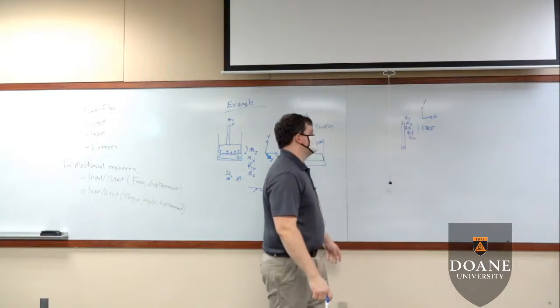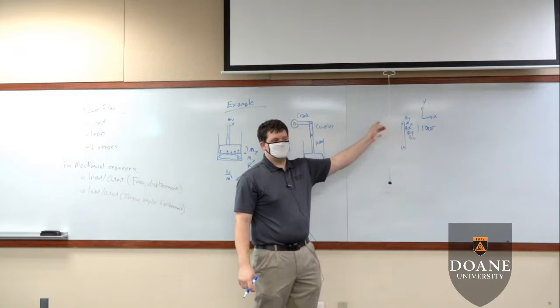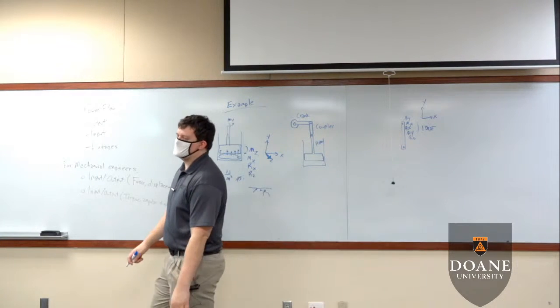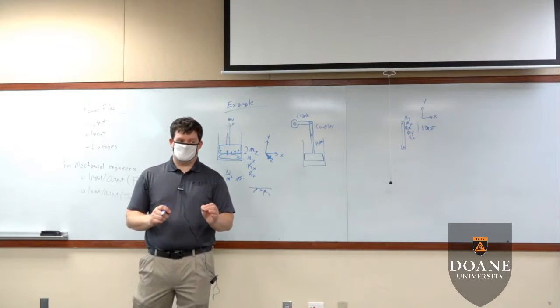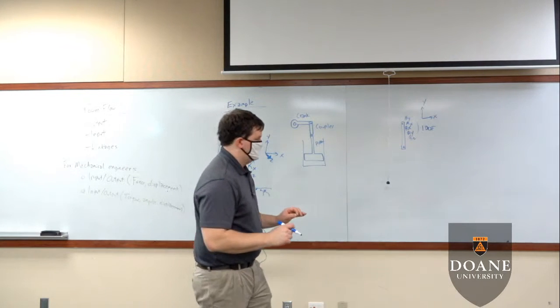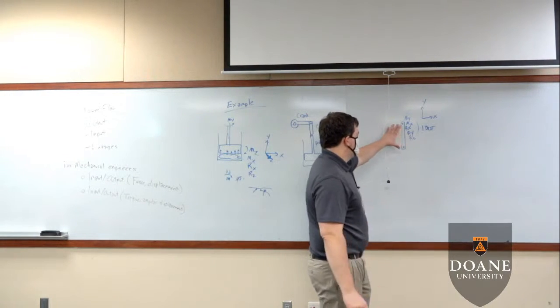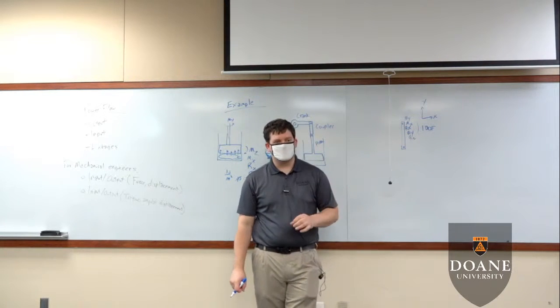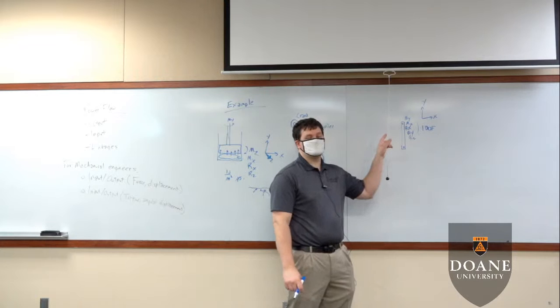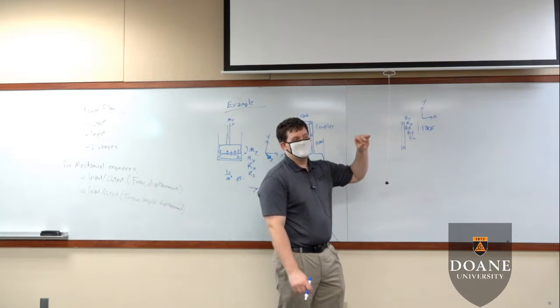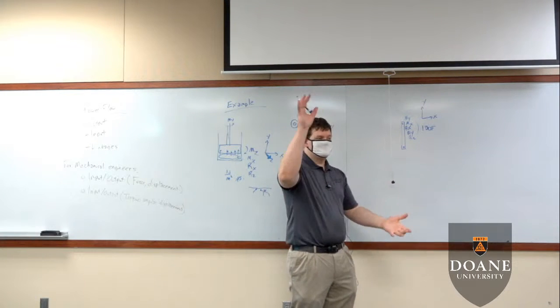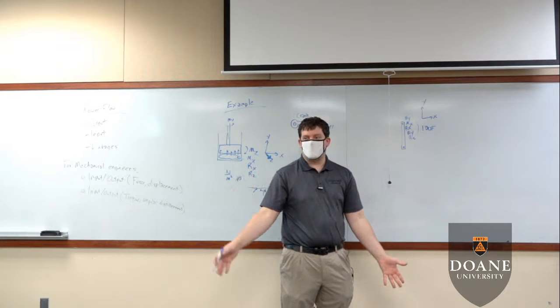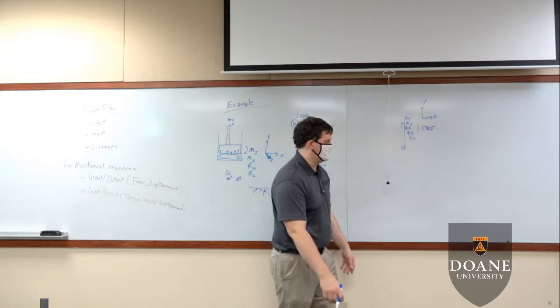Now the question here is, because the joint itself does not create a boundary condition in the Mz direction, if this component rotates in the z direction at all, it is not because the joint is creating a boundary condition. It's because other outside external forces are doing that.